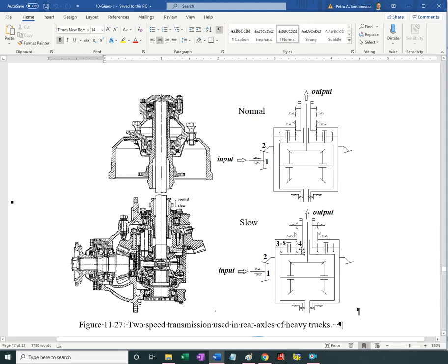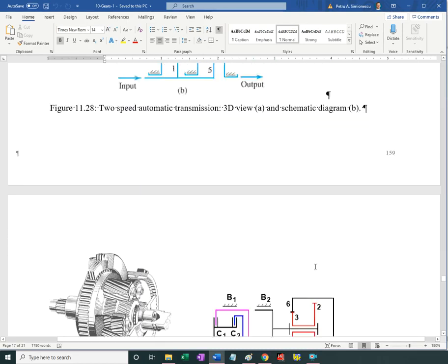So by doing so, I have the sun gear of the planetary unit fixed to the ground, omega 0, and then the way the unit works is as a planetary gear that has the ring as input and has as output the carrier, the planet carrier. The planet carrier is the housing or the carrier of the bevel gear differential. Okay. All right.